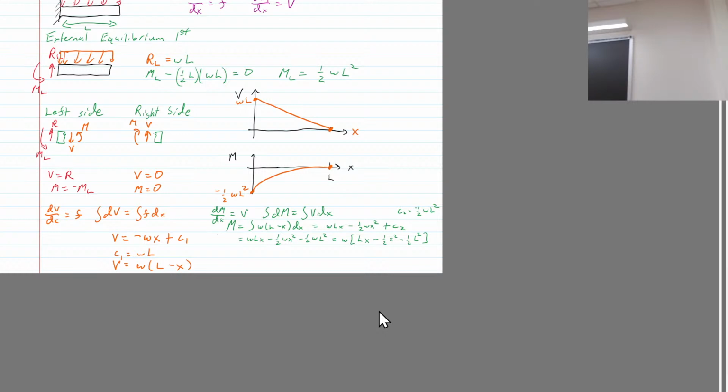Can you go back to my diagram, because I just want to make sure, yes, it's PZ times A. That's about the axis, and that will be a negative my over I, but it's going to be tensile. Are we doing PZ? Yes, PZ's into the board. I'm doing the positive for now, apply negatives later.